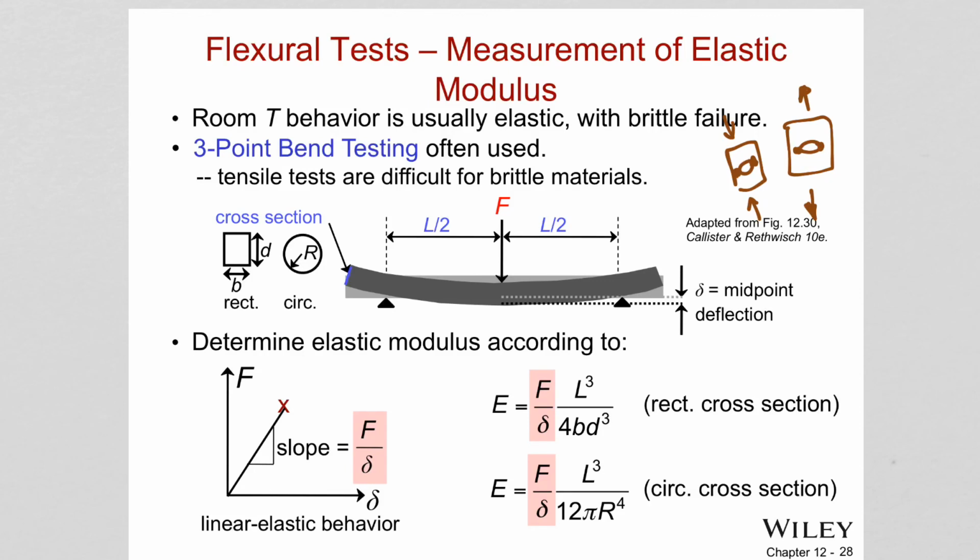So there is this test called the flexural test, which exposes the material to bending. Certain parts are in compression, certain parts are under tension. If you bend the part, this surface is going to be under tension, right? But the inner surface will be under compression. So this test is preferred for measuring the mechanical properties of ceramics. It makes a better comparison between different ceramic materials.